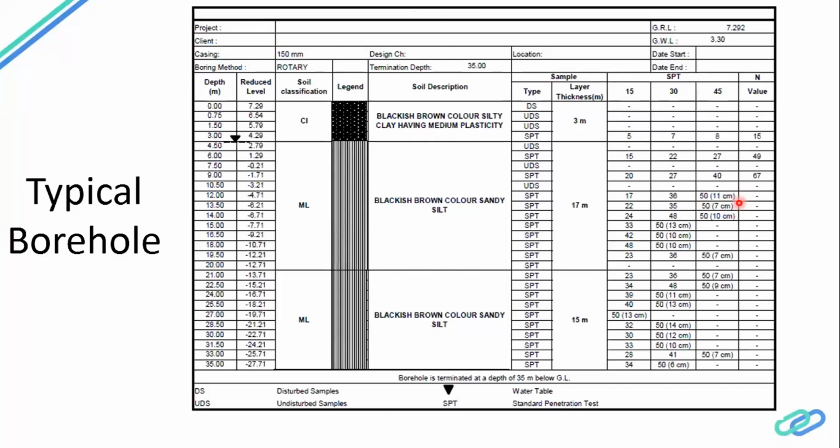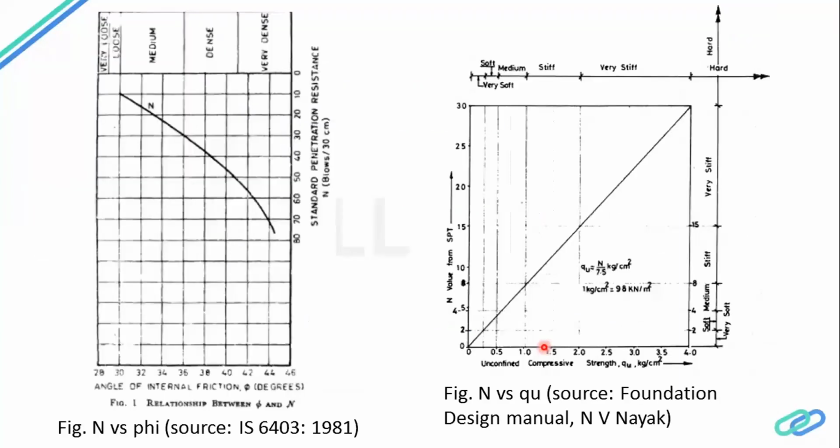But still, it is a soil. They are able to use the same drilling bit for doing the further boring. So here we can see it's all dense soil. So in very dense condition, they will not be able to retrieve the undisturbed samples. So here we can see all the tests performed is SPT only, because undisturbed samples they cannot retrieve. So only disturbed samples collected from the split spoon sampler will be used for the testing. Moving forward,